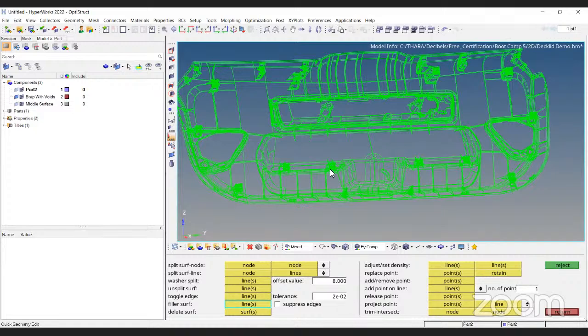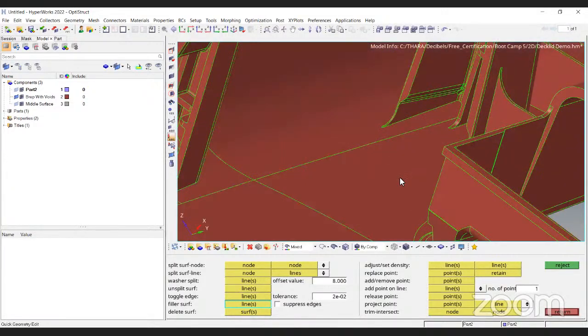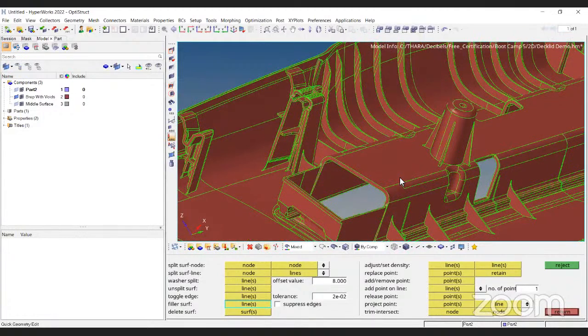So why is the mid surface very important in 2D meshing? Basically, in the 2D meshing we are going to do today, we are not going to create the mesh on this top surface. We are going to extract the mid surface. So why do we need to extract the mid surface? Basically, the idea behind extracting the mid surface is when the component is plastic. We have seen the materials, as I said: steel, aluminum, or plastic. So for these materials, we are going to extract the mid surface. And when we need to create the 2D elements, we need to extract the mid surface.